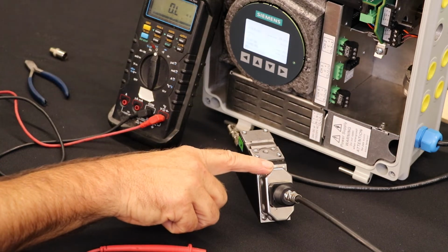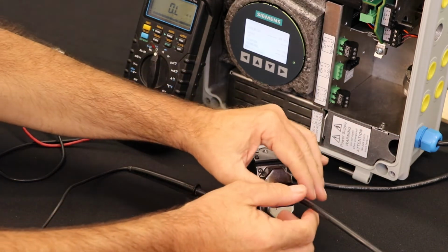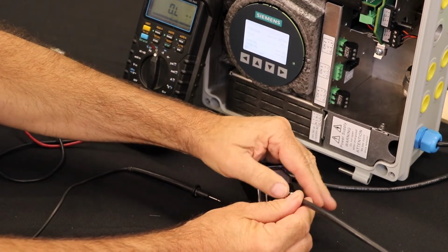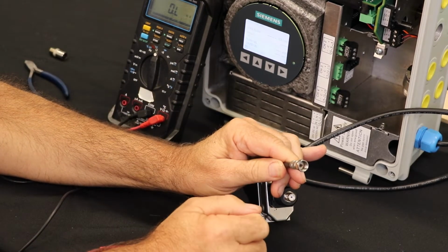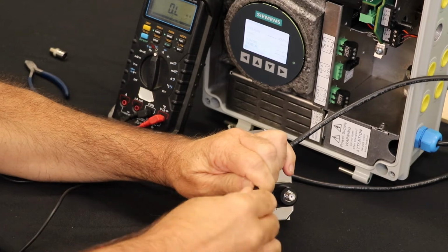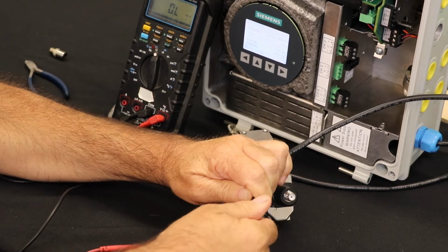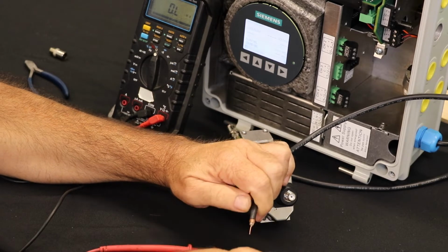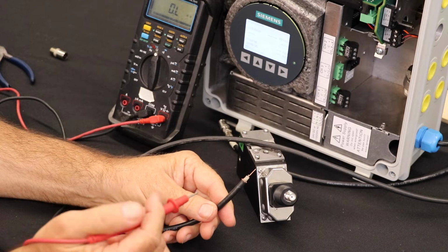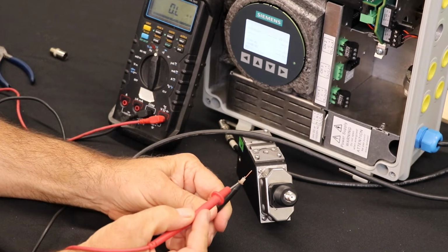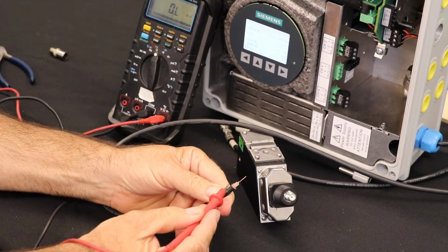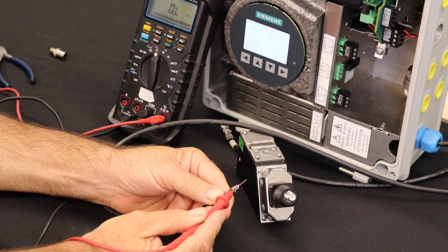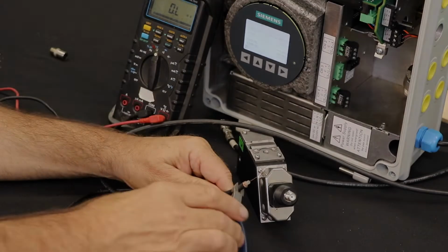Okay, I've located the sensor which is reading open. So I'm going to take this connector off. And this is a twist-on F connector. So I'm just going to twist it off. Now, upon closer examination, what I notice is that this braided material, by and large, is missing. Ordinarily, when this is stripped correctly, the material of the braiding should be up to the end of where you see this insulated part. So I'm going to snip this off.